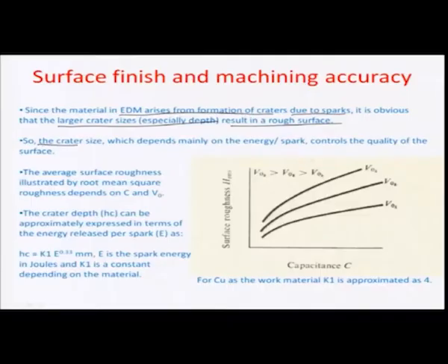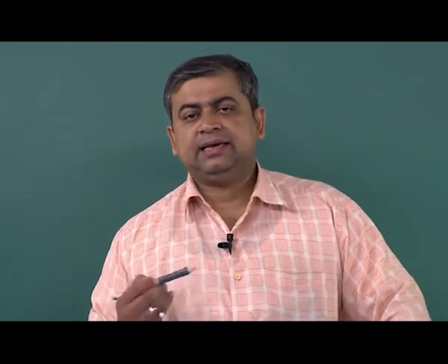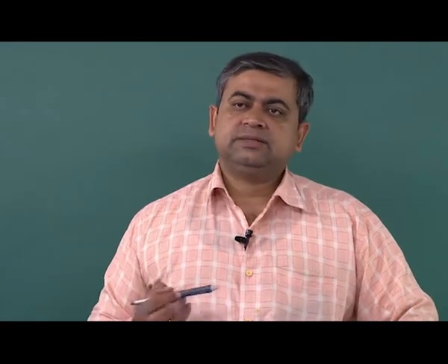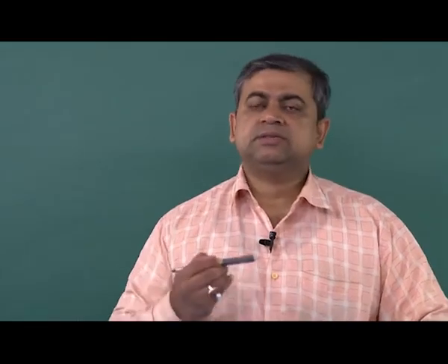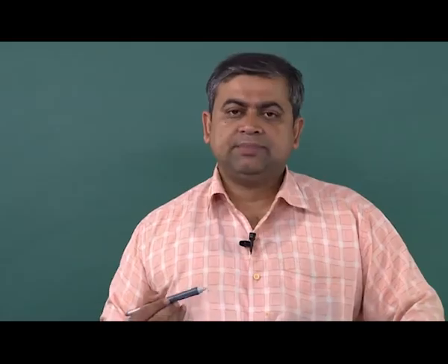The crater size, if we look at it mathematically, as we had done earlier, mainly depends on the spark energy. If you are releasing this energy as a packet with a high intensity, obviously the crater will be deeper, and vice versa, if the energy delivered is smaller and the frequency is probably larger, then the crater would have a lower depth.